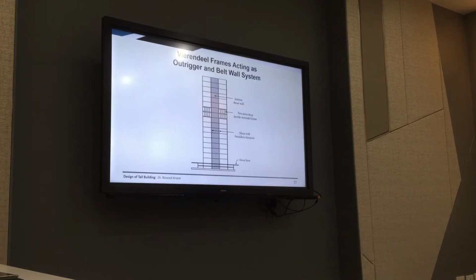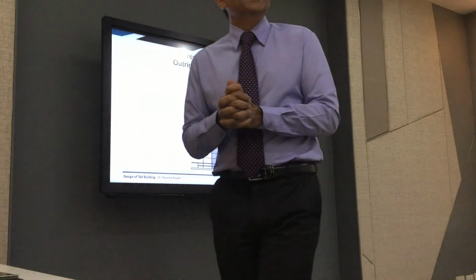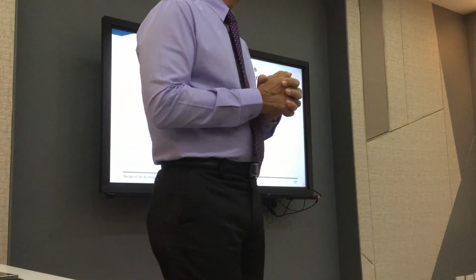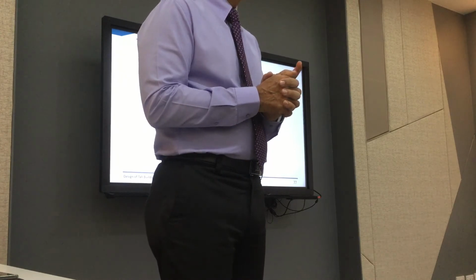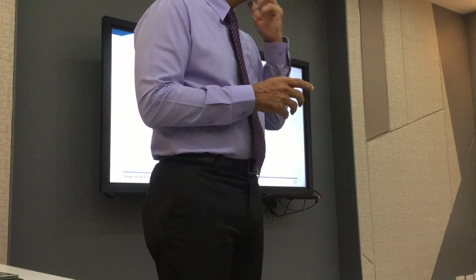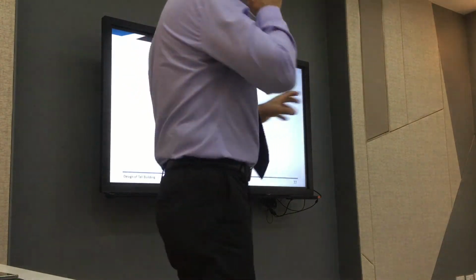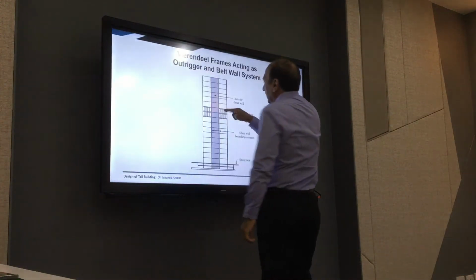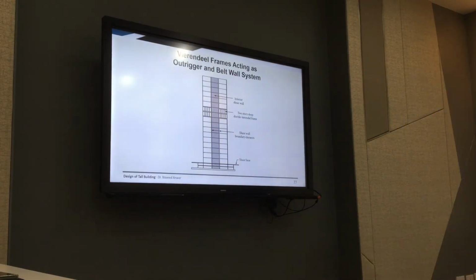I could give you an assignment, but then you will ask me to arrange a trip and arrange a van for you to go there. But that is a very good example of Vierendeel truss they use on that walkway bridge. One of the few bridges where you can see that very clearly. So they designed it as a frame, but it's a truss. So sometimes we can design outriggers with openings using the Vierendeel ductile moment frame concept, right?